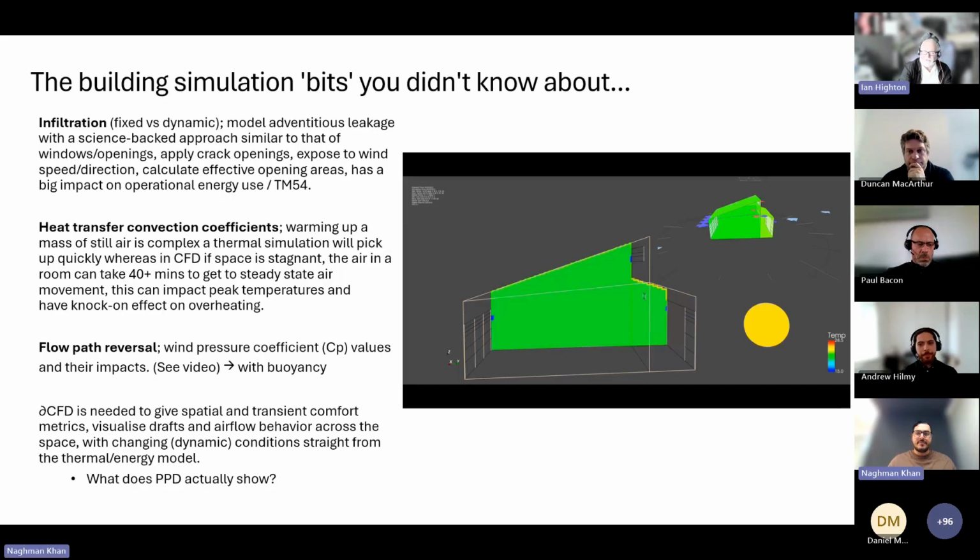And this was purely thermal control, wasn't it, Andrew? Just temperature based? Yes, exactly. This is just temperature-based thermal control. Here you can see we're in the evening now, and the apertures have opened again. You're getting much cooler air from outside coming in and cooling down the space. It's worth pointing out we can do CO2 as well and do them both at the same time.